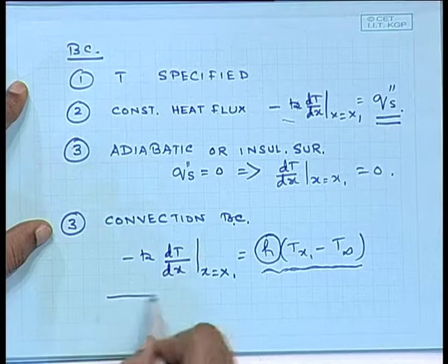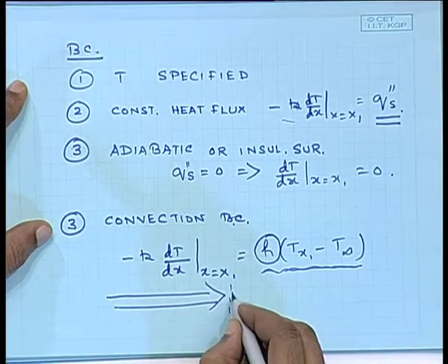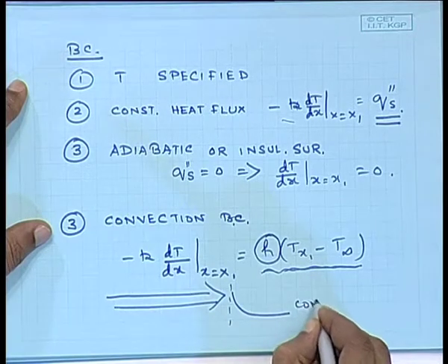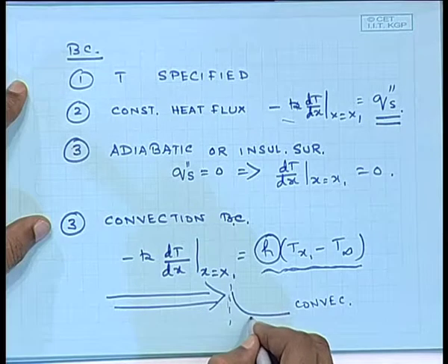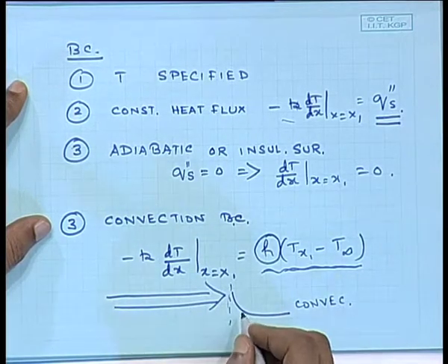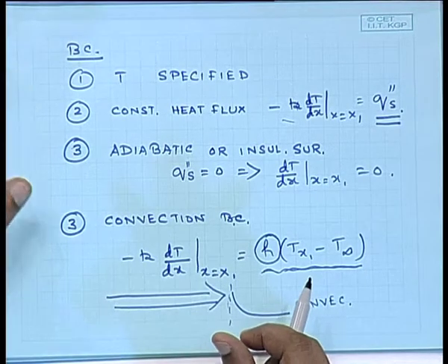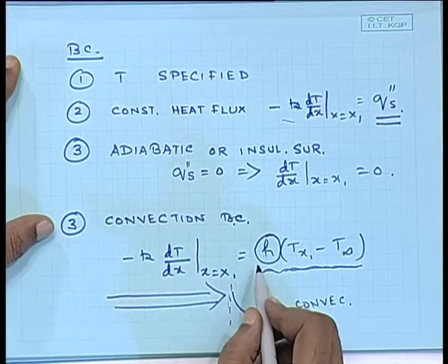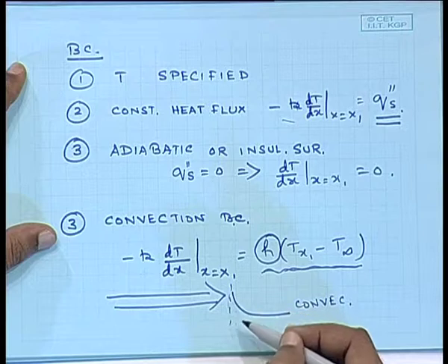So, the amount of conductive heat coming to a specific location must be equal to the convective heat which is going out, and I think we spoke about the boundary layer which forms near the solid surface, and we emphasized that these boundary layers are generally very thin, and you can increase H by increasing the turbulence on this side.